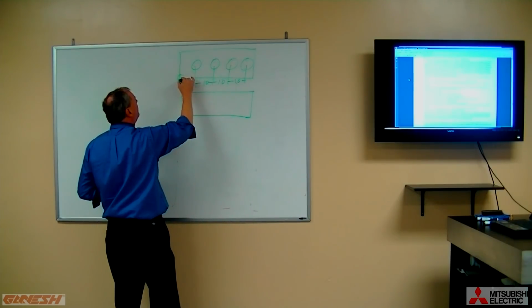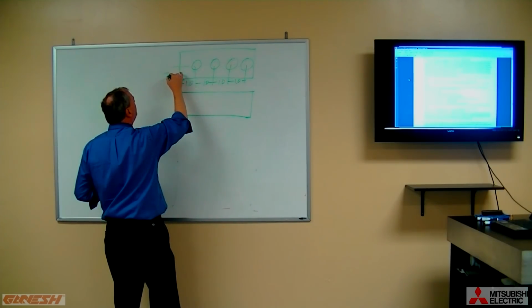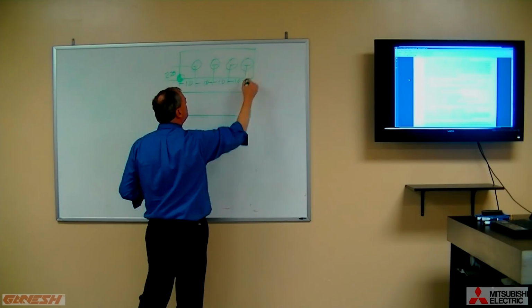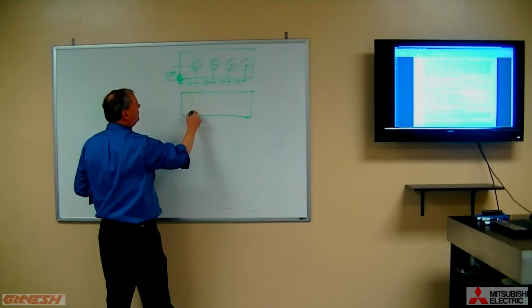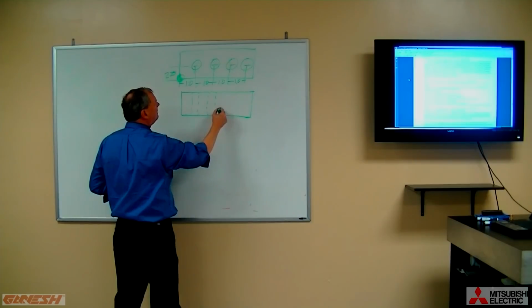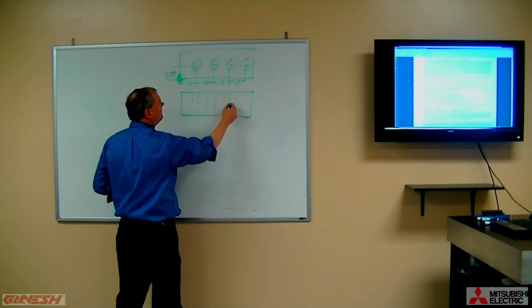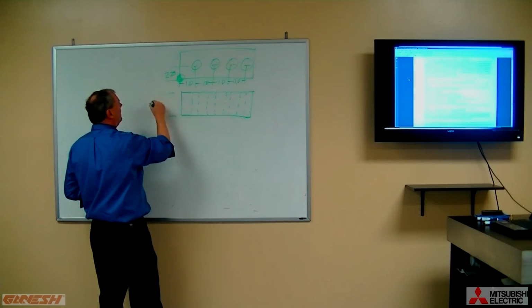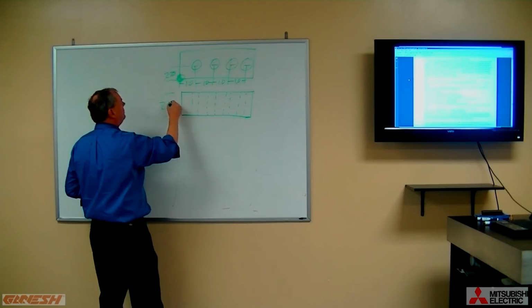And our x and y datum is right here. And each hole is 2.25 up in Y. They're all on the same line. And they all go through this thick piece of bar stock. And it's, well, let's just say 2 inches thick.